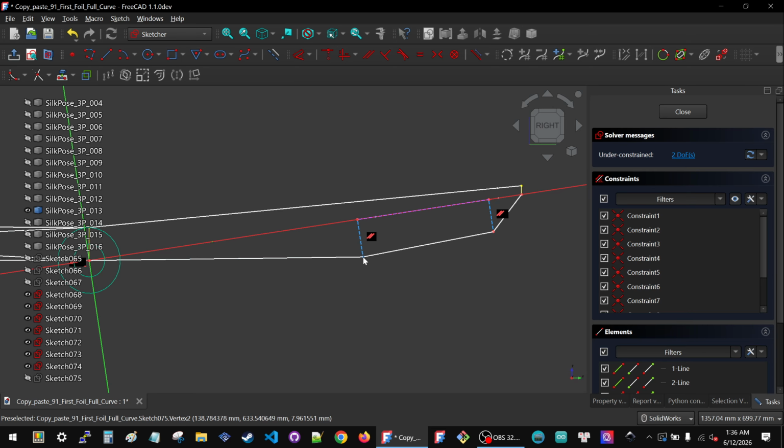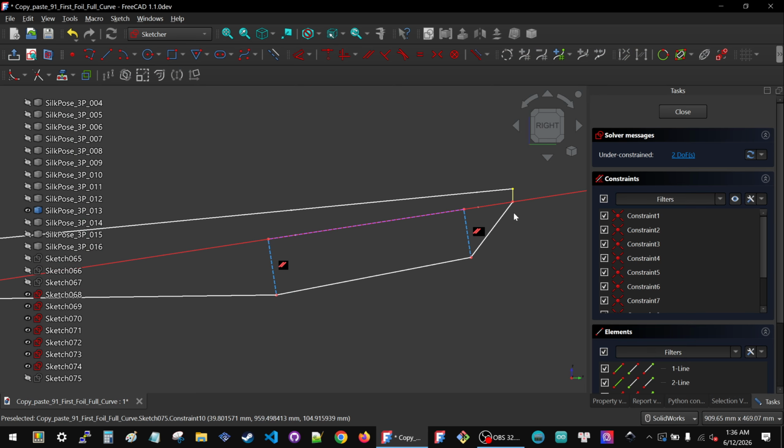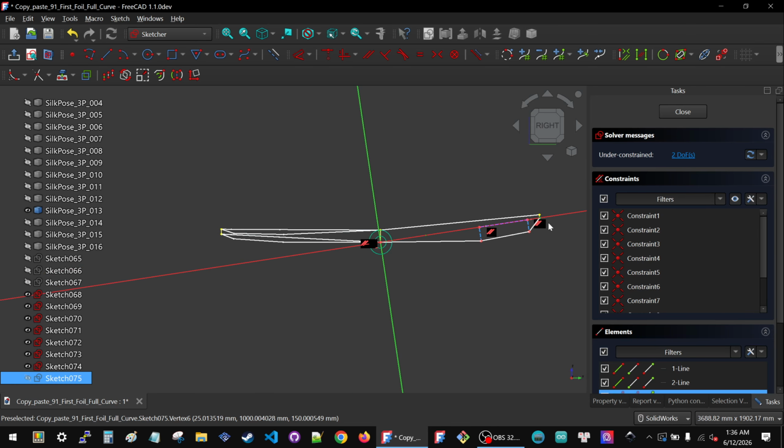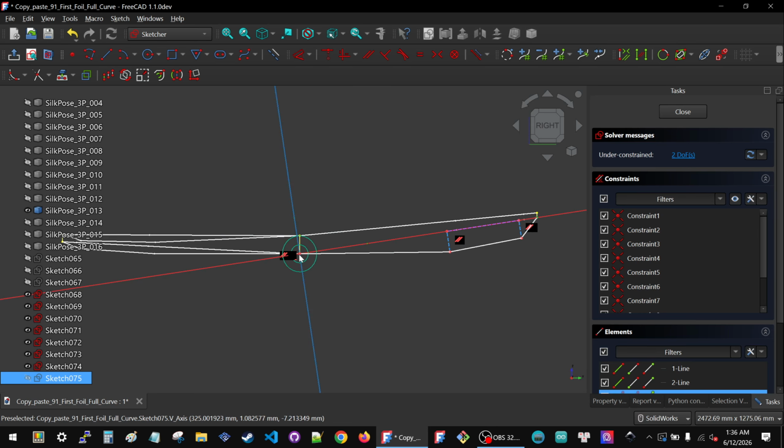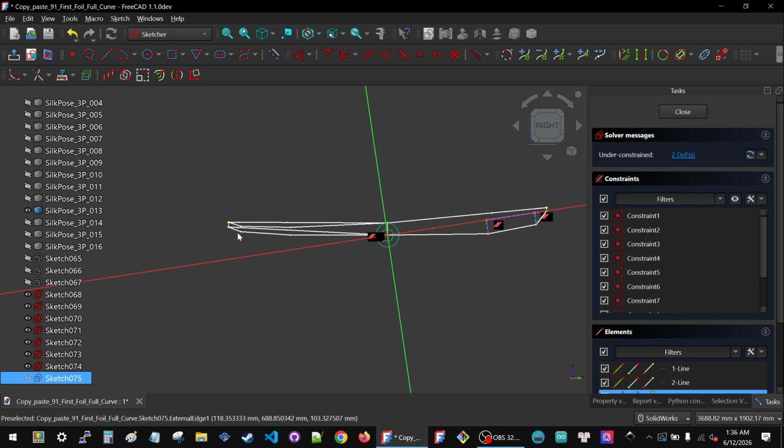So I basically like these values. But like last time, I'm going to say that they're in reference to the front. That way this will allow me to compare the way I'm dimensioning the tail to the way I'm dimensioning the nose. You could create absolute dimensions from here to the origin, but I like the idea that I have a scheme front to back.